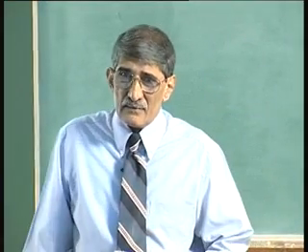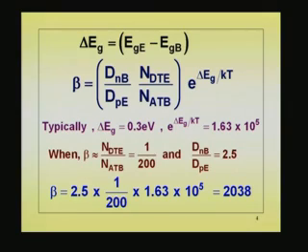In fact, in the bipolar conventional transistor, you have a problem the other way. You have a problem where the band gap in the emitter is smaller than the band gap in the base, due to the heavy doping effects. Okay. So, in fact, when you do a device like this, you overcome even that. Just to point out what actually is happening, just one or two sentences I would like to bring out.